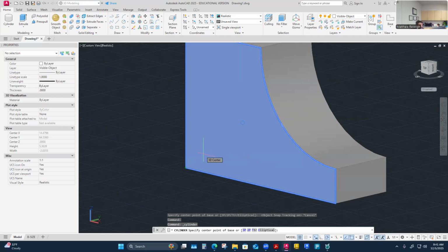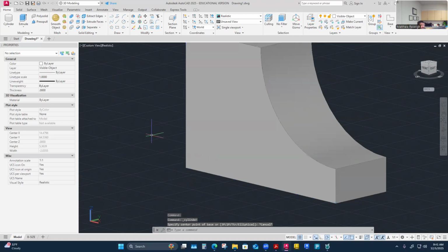Rather than try to beat our heads against the wall, let me show you how another way would work, and I like to show this too: we can draw on this surface with 2D drawing. Right next to the editing here is almost like a crunched-in draw panel. Our 2D drawing commands are right here for the most part: lines and polylines, even shapes and rectangles, and our circle commands. We have access to the commands we're used to here. So I could do some construction work here.